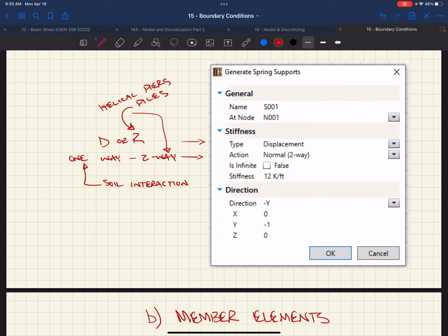It's the resistance for your soil to actually push against. If you tried to have that wall push against the soil on the outside, how much does that soil resist it? So you should consider it in some cases, you should look at it. Usually that pressure is pretty consistent with an at-rest or an active earth pressure. And so you've already designed the wall for that pressure, so in an earthquake event you might have already considered it.